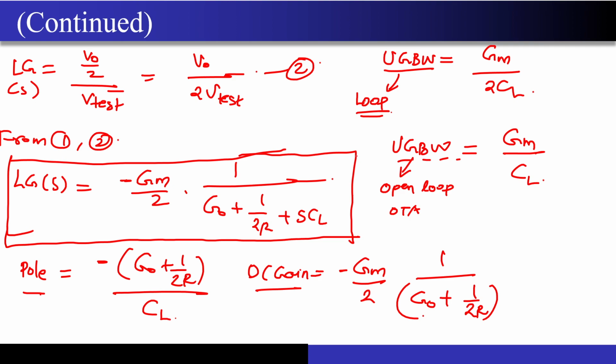We first stabilize the system considering that beta is equal to 1, for the case where we are considering the dominant pole or Miller compensation. In the case of feed forward compensation, the story changes, but we are not looking at that particular case over here. Just remember and imagine why, if I reduce beta from 1 to half, my UGBW actually reduces by a factor of 2.